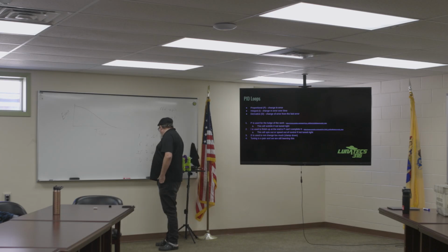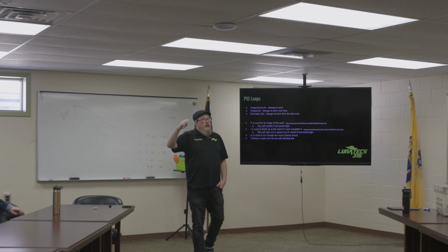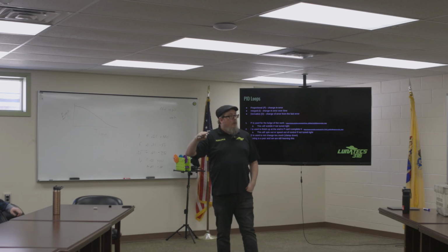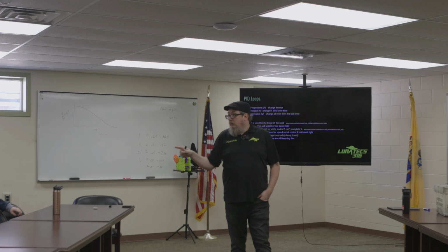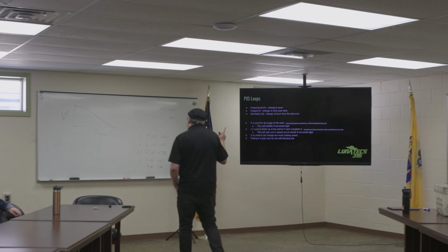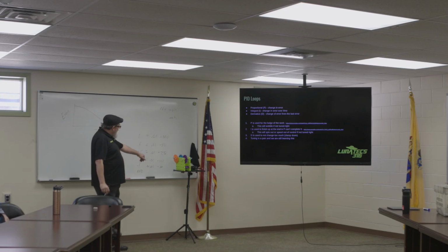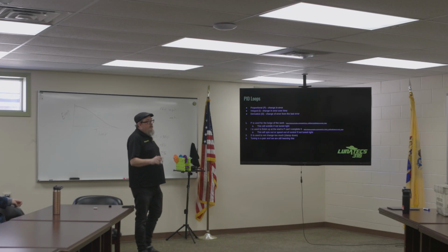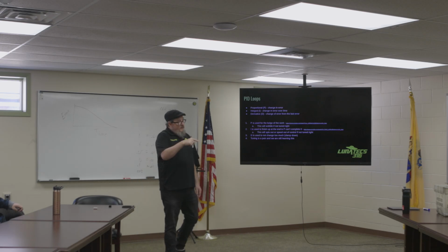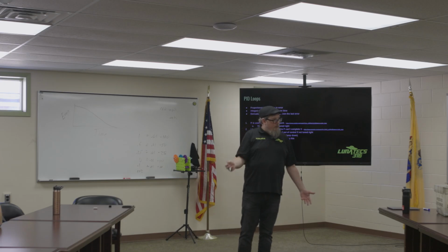Right, because all of a sudden now the error becomes 10 because it starts slowing down. It was at 100 miles an hour. We stopped giving power to the engine, and now it slows down to 90 miles an hour. What's the error when it's 90 miles an hour? 10. Multiply that by 0.01. How much power do I give to the engine? 90%. No. 9%. No. 0.09. 10%. If my error is 10, and I'm timesing that by 0.01, what is that? 0.1. And then you convert that to a percentage, that's 10% power.